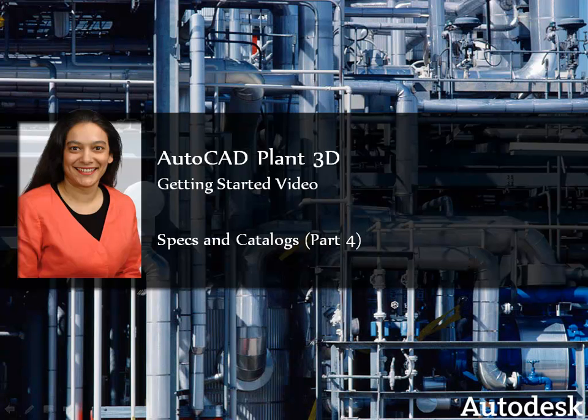In this video, we're going to create block-based valve bodies and actuators. We will then assign a default actuator to a valve body, and then show how an actuator can be set depending on the type and the size of the valve.